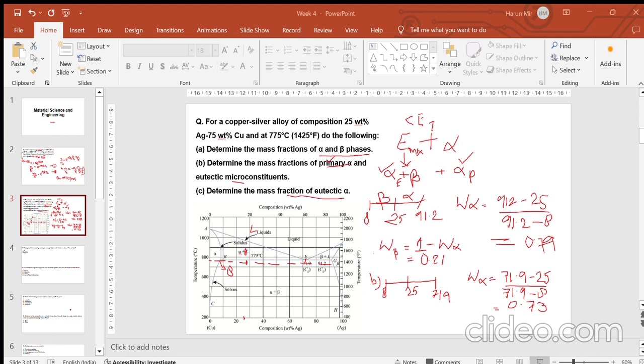Ma'am, how would you define the solvus line? We have defined liquidus line, we have defined solidus line. What is the definition of solvus line? Solvus line is nothing but a phase boundary between your one primary phase, which is alpha, and your two solid solutions. So you have a solid solution of alpha plus beta. It just gives you an idea how soluble your phase is. For example, how soluble your B atoms are in your alpha phase.